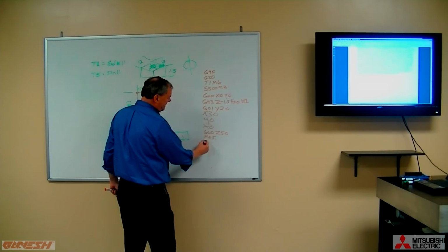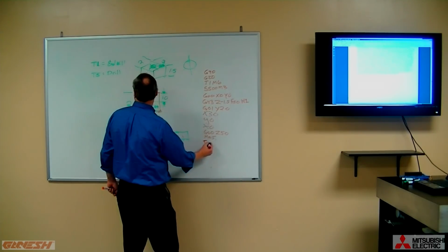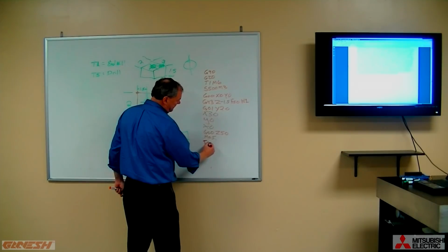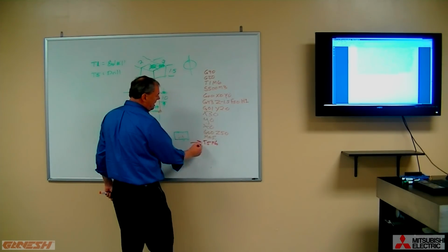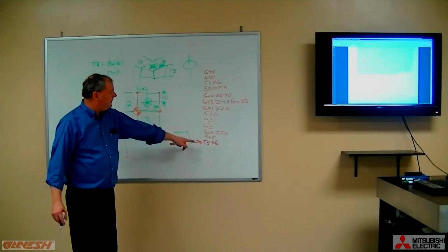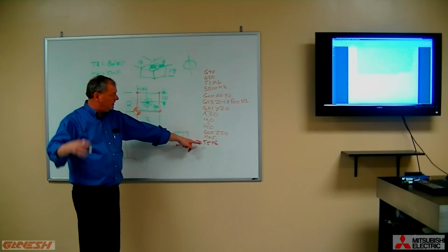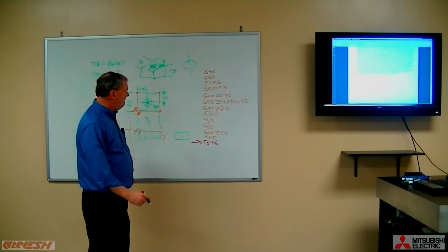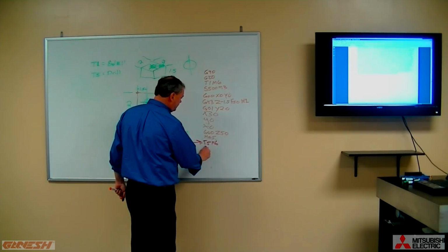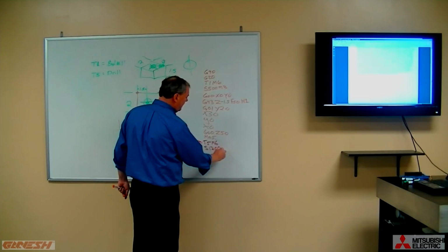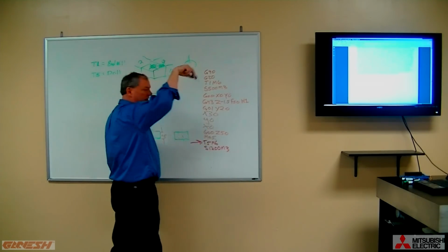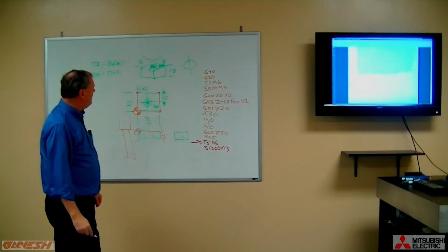And we're going to say, or I'm sorry, T5 is what we called it. T5 M6. So now we're loading T5 into the spindle with the tool change arm. And let's turn on the spindle speed. I'm going to say S1200 M3. So now our spindle is running at 1200 RPM.